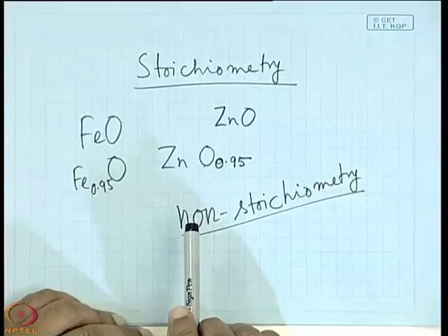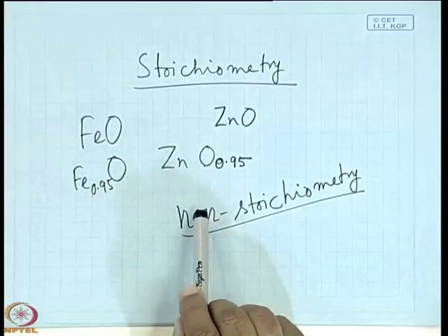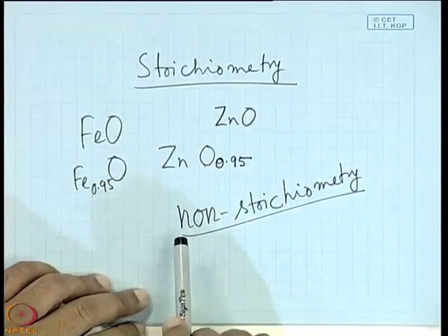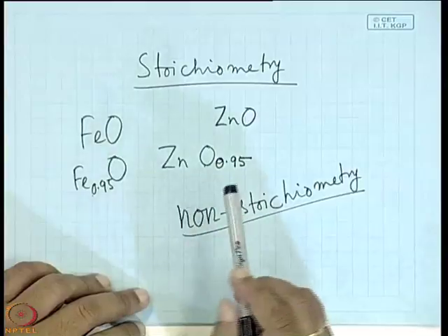The dopant will be compensated, because there is already a vacancy. So, the dopants will be compensated by the vacancies. As you go on increasing the doping concentration, there will be compensation. This is known as self compensation, because there are enough vacancies inside the material.